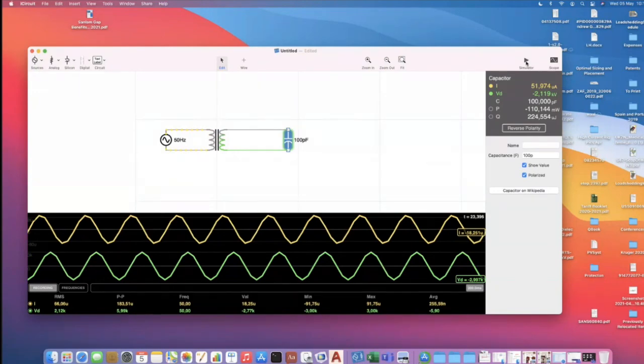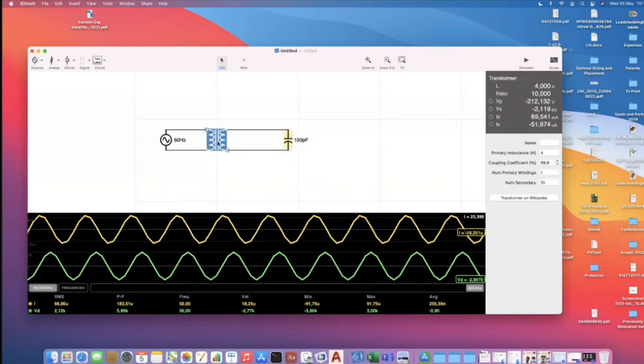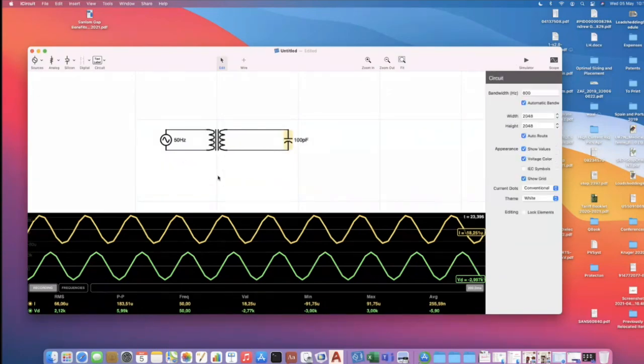The real power is almost zero, but there's still reactive power. So when we refer to high voltage equipment or testing equipment, we need to consider the apparent power, not just the real power. And that's what gives it that power rating.